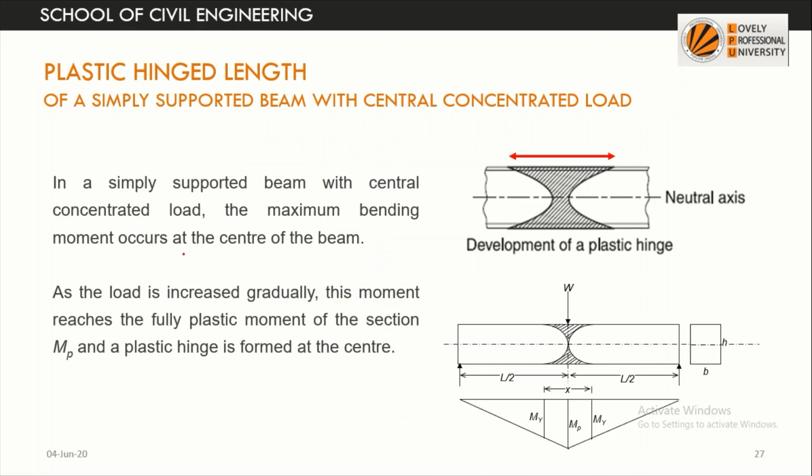So there is a small derivation in which we'll assume a simply supported beam with a central point load, and the maximum bending moment will occur at the center of the beam only. As the load is increased, the moment also increases, and at a stage the fully plastic moment of the section, MP, is reached and the plastic hinge is formed at the center. So for this case we are trying to find the length of plastic hinge. This load corresponds to a load which will cause plastic moment.